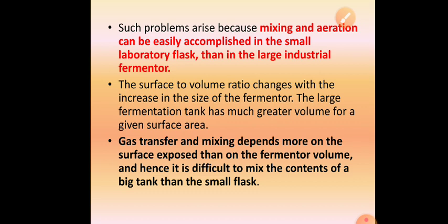Further, the surface to volume ratio changes with the increase in size of the fermenter. In a large fermentation tank, the volume of the liquid medium is greater for a given surface area. In a small tank, surface area is more, volume is less. But in a large tank, volume is very much greater as compared to the surface area. Gas transfer and mixing depend more on surface exposed than on fermenter volume, and hence it is difficult to mix the contents of a big tank in comparison to a small flask.